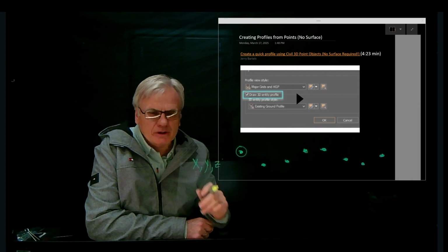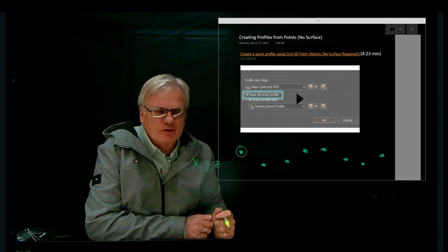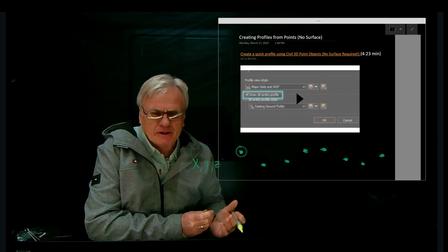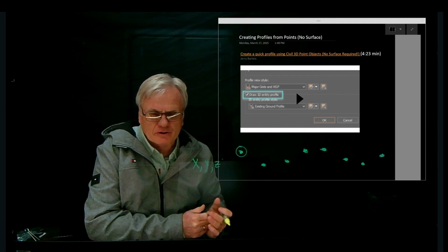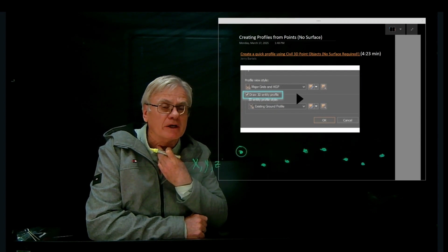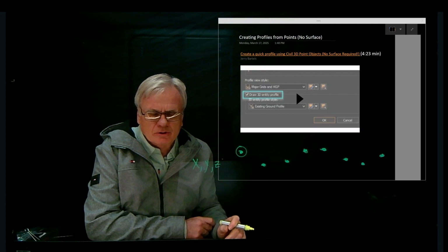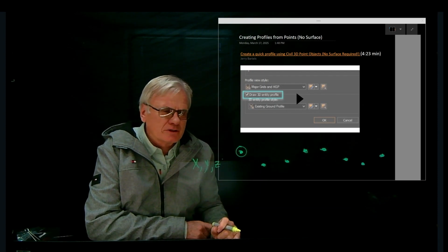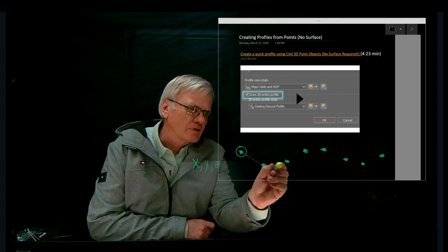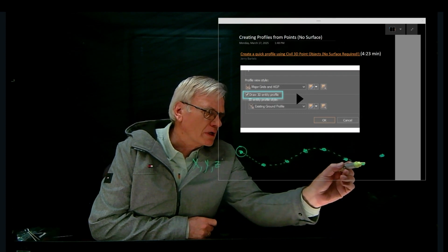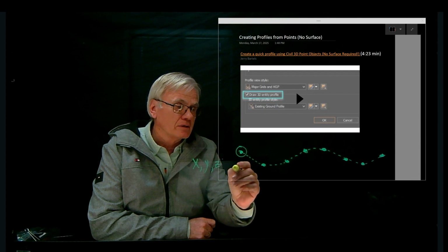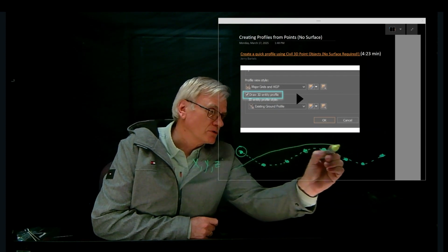Well, we can use Civil 3D, and it's explained in this video. I'm not going to go through the time to show you how to do it, but this is a very practical case where you may just have some survey data along a horizontal alignment, and you've shot these X, Y, and Z coordinates with a total station, a GPS unit, or some type of transit system with a level. Maybe these have a trend, if we connect the dots, that shows like this, and maybe we're wanting to design a highway that comes through here and might do something like that.